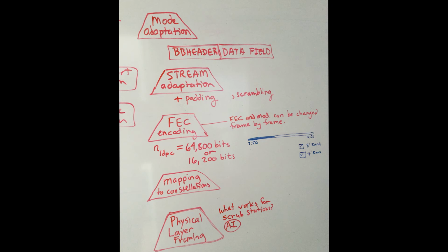An open question that immediately occurred to us is how minimal of a station can be supported? And the answer is probably going to be in the specification dealing with the physical layer framing, or part of the answer. Driving it down as low as possible is going to be fun and challenging. What we're anticipating is that the space teams will obtain an implementation of a DVB-S2X transmitter. Talks are already underway for this. Phase 4 ground is going to engineer the various DVB-S2X receivers. Standard documents are already in the repository, and work is beginning, so get off the bench and hit the books.